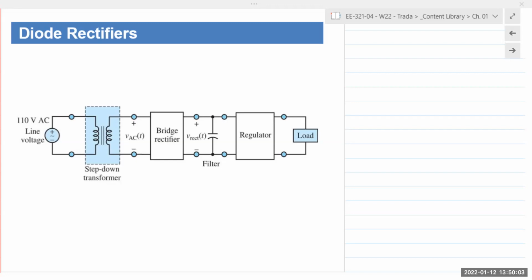And that's the reason why manufacturers will tell you not to use generic chargers. Even generic chargers are smart enough nowadays, but if you buy a really cheap one from Amazon or eBay, and the circuit's not designed very well, if you connect your tablet to it and the tablet says, I'm fast charging, I need 5 amps, the charger can only supply 2, but it will send 5 amps. What will happen? Overheat and explode.